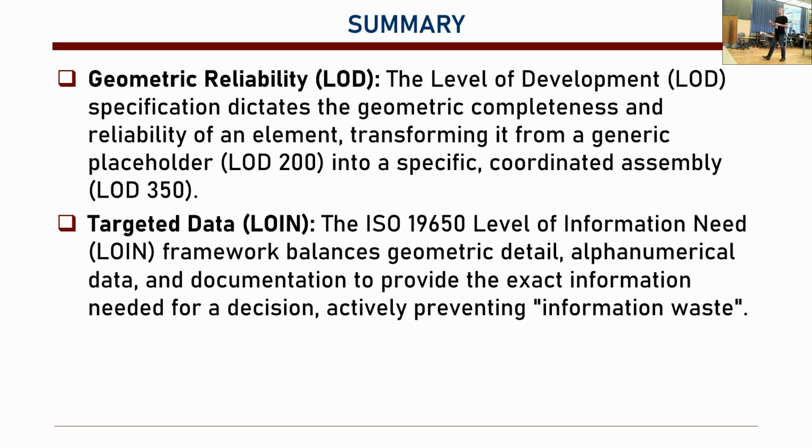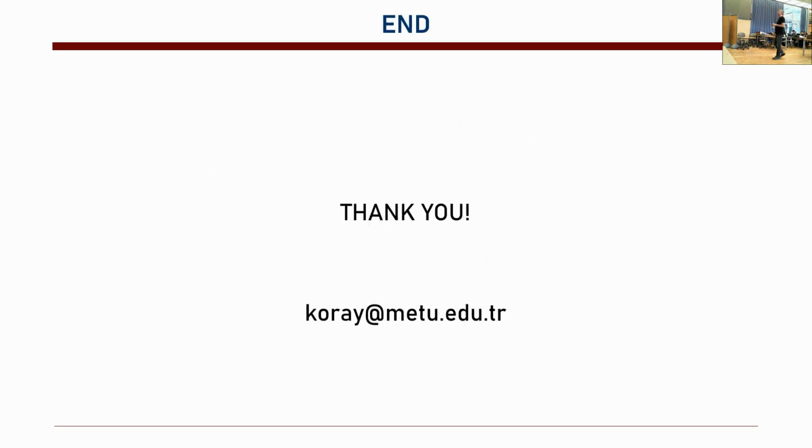And then we have targeted data, LOIN. ISO 19650 defines the level of information need framework. Okay? So it balances geometric detail, alphanumeric data, and documentation, so that we have the exact information needed for decision, so that we prevent information waste. Okay? Good. I think this is the end of it.